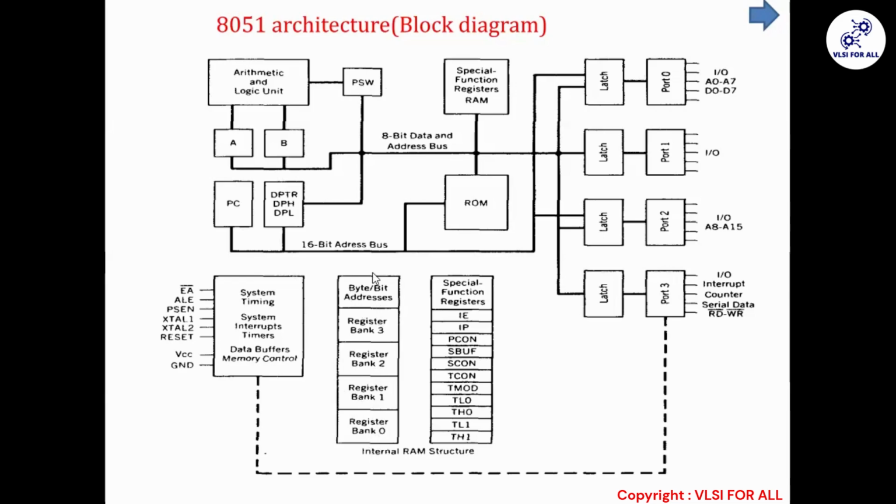After that, the upper part of the RAM is bit addressable or byte addressable. It means we can address a single bit of this RAM. If I need just 1 bit from there, I can address it, or I can go for the complete 8 bits, which means byte addressable, depending on my requirement. So that is how part of my internal RAM is there.